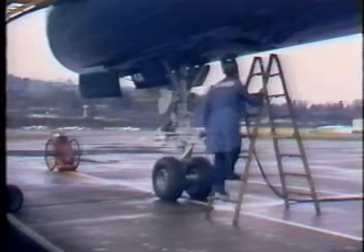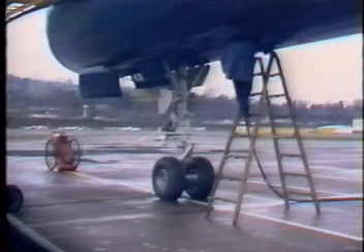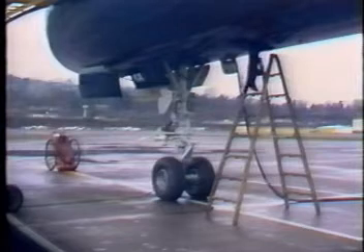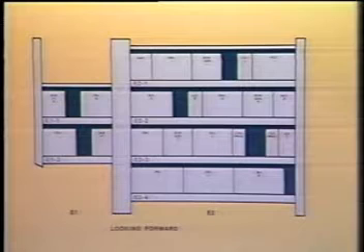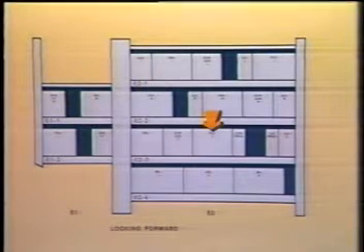The flight control computers, or FCCs, are located in the main equipment center, on the E2 rack: the left, right, and center FCCs. The FCCs provide the main computing functions for the autopilot flight director system. All three computers are identical, relying on airplane wiring to identify the left, right, and center channels. Cooling is provided by forced air.